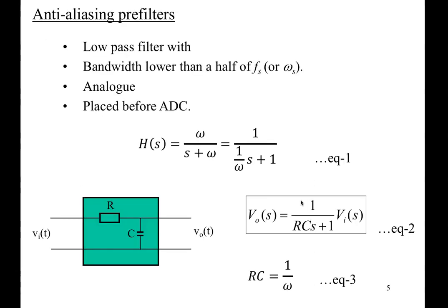And we also safeguard that. Say, for example, we choose a particular sampling frequency because we know the maximum frequency range the controller has to deal with. But other signals may creep in, like noises in a system, which is not something you can expect or predict.